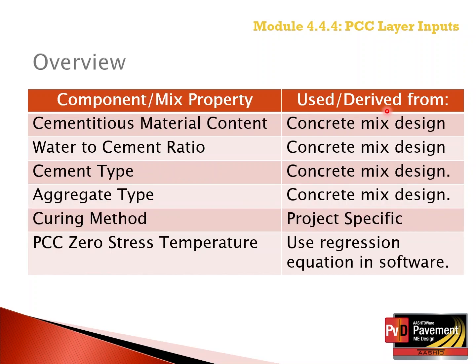In summary, the default values and where the component mixture properties are extracted from for the component mixture concrete properties needed for the PMED software are listed on this slide. The component mixture properties are also listed in Table 10-4 in the MEPDG Manual of Practice.